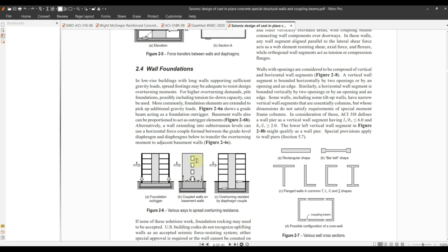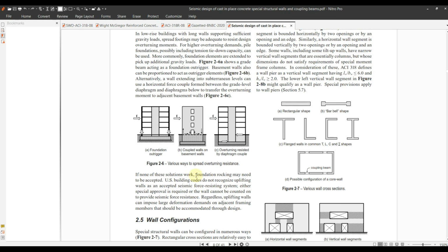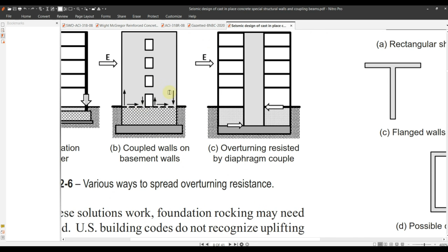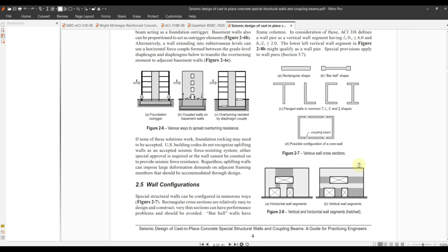So a shear wall is always a fixed support. Okay. So here it is compression, here it is tension. So there is always a bending moment at the base. So you must design your foundation for the associated bending moment. Okay. If you do not design for the bending moment, then your shear wall concept used here will not work actually, because your foundation will rock before the bending moment can develop at all. So it will not be any logical thing at all.